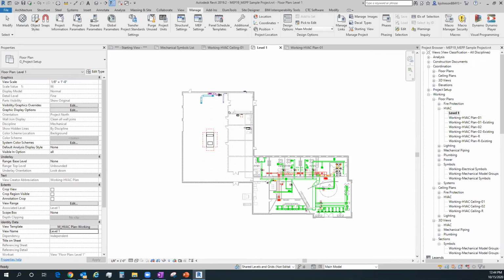That would be another area where a bug in one version is fixed in another, and vice versa. When somebody saves and syncs, it's fine, and the next person saves and syncs, the bug is still there, and that may cause a file corruption as well. So have everybody on the same version within the office for each Revit version out there. So 2018, 19, 2021, each of those are the Revit versions themselves, and then the hotfixes would be the .1, the .2, .201, whatever those might be. Try to make sure everybody's on the same version of Revit across the project.